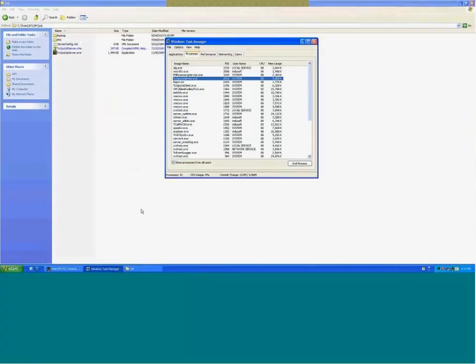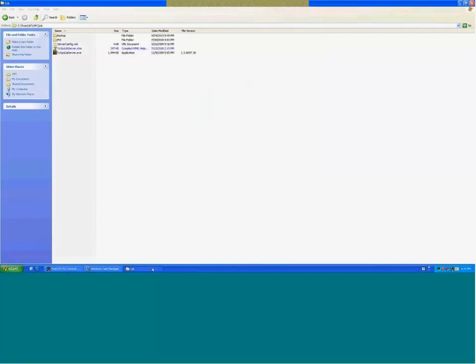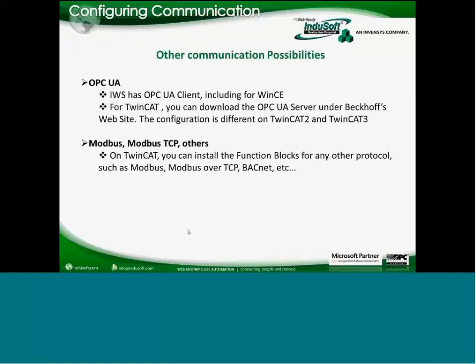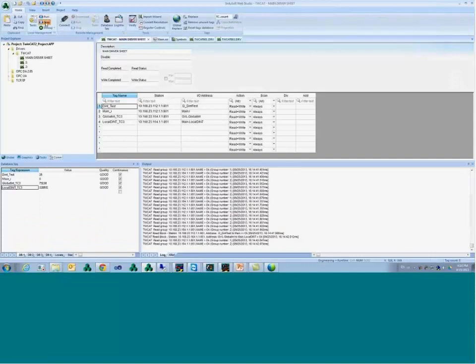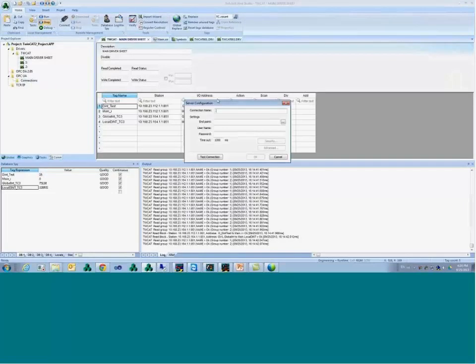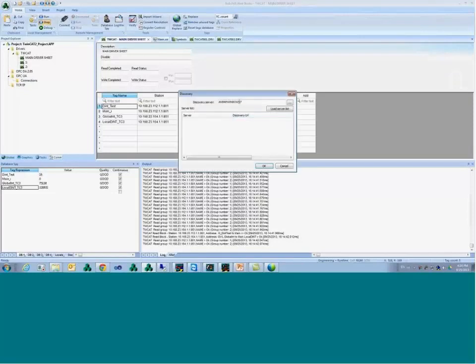All right. So I do have here the TwinCAT OPC UA server service running. Not sure if that's still running because I've been running for a while here. So if I go back to my Web Studio, I'm going to stop this and configure, on the same project, an OPC UA connection to that PLC. The first thing I do is create a connection. I'm going to call it TwinCAT. I'm going to connect that to that PLC, which is under WinXP-OPC.